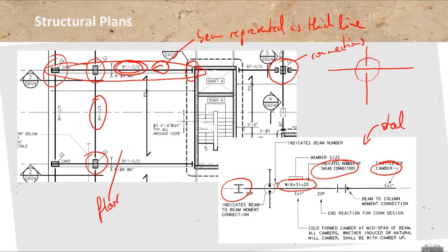And in this case here, the span direction is north-south, so basically up-down in this plan. And it's indicated with a squiggly arrow that you can see right here. And then of course, if this is a one-way system, as what we have here, it looks like that. If it's a two-way system, then of course you'd have something like this here, which we don't have. So I'll take it back out. But that secondary symbol shows you the floor span.